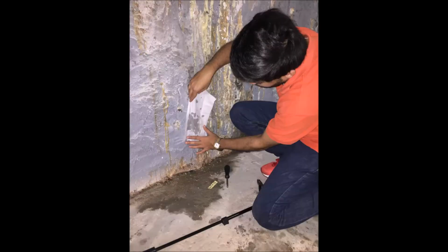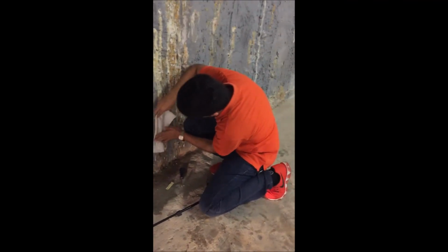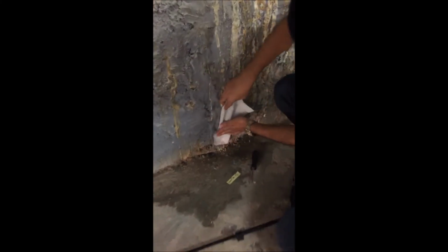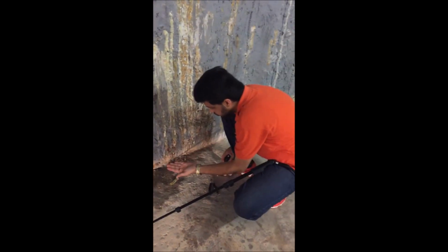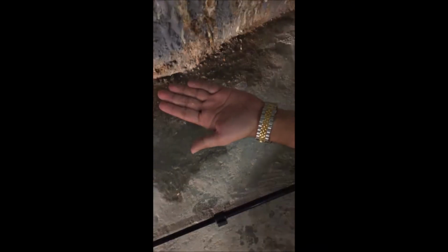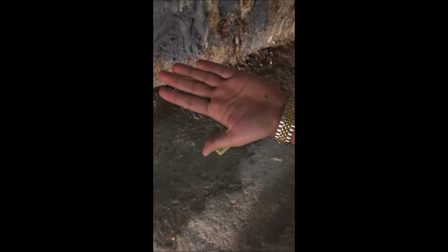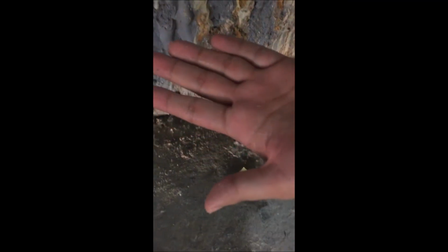As it can be seen on the video, the wall is entirely dry. I'm using my hand on the wall and checking the moisture level. My hand feels dry when I put the hand on the wall. So I use the tissue paper to stick on the wall to get the moisture. In a basement of this condominium, the problem is moisture under hydrostatic pressure since it is the 6th floor beneath the surface of the surrounding ground, and it can range from simple dampness to running water depending on the circumstances, as it could be seen on this video.